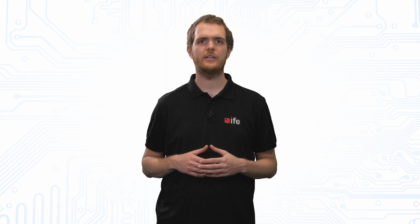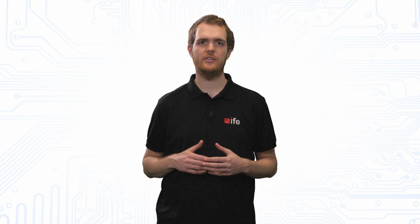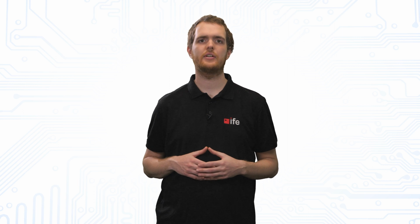For simulating the EMI-induced offset voltage, we configure the amplifier as voltage follower with a DC input voltage of half of the supply voltage. On top of that input voltage, we superpose a sinusoidal disturbance. Finally, we obtain the change in DC output voltage by averaging the output voltage. This offset voltage is referred to as EMI-induced offset voltage. For our first EMI investigations, we use an EMI amplitude of about 500 mV and sweep the frequency from 1 MHz to 10 GHz. This results in this plot.